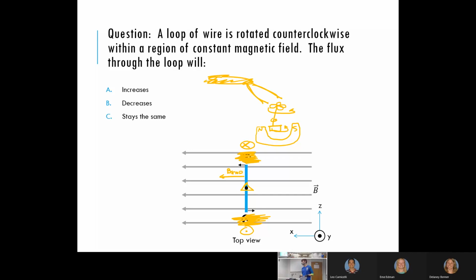That's actually a real big problem in California right now. It's called the duck curve. Okay? So what happens, California has a lot of solar. So if you look at a coal-fired power plant in California, if you plot its electricity as a function of time during the course of a day, you'll get something where it's high, high, high, then it drops down to being really low, and then it spikes back up. It's called a duck curve because it's supposed to look like the outline of a duck. The head going down to the back and then back up to the tail. And it's a real big issue.